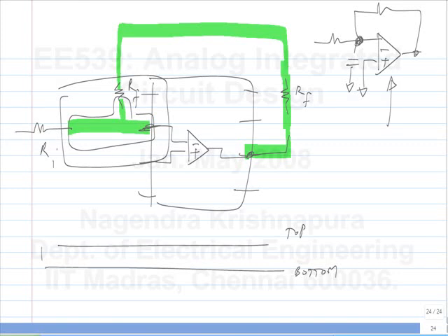So of course, as far as the schematic is concerned, it doesn't matter where you put this. It's assumed that this whole thing is one node, this whole thing is another node, and so on. But in practice, the area on the inverting node must be made really small. Okay, that's the only way you get good performance from the amplifiers. Okay, let's say we do all this.